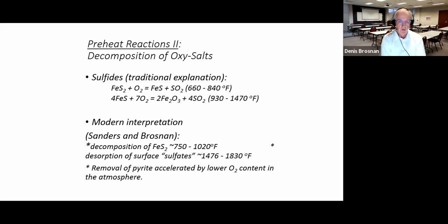The most interesting example I ever had of that was bricks on a school in Hershey, Pennsylvania. Many of you will know that Hershey, Pennsylvania, in the United States is where Hershey bars were made, chocolate bars, for the first time. And of course, they're brown in color. In a particular case, white bricks were used on the structure, and the iron sulfide was not burned out. And over a period of about a year, the water that impacted the bricks from rain dissolved the iron sulfide. It came to the surface and made a brown deposit on the bricks.